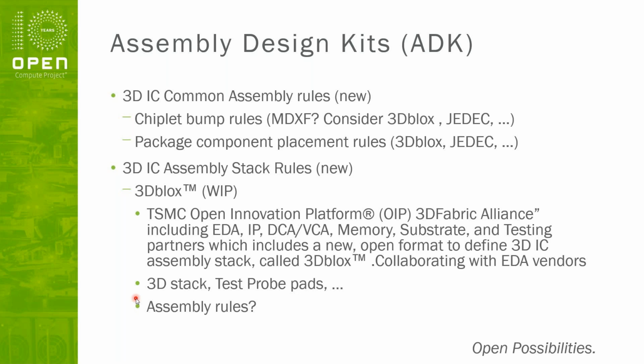One of the things that is not addressed in MDXF are rules outside the die. So this is more in the package, different rules. It may be die-to-die rules and spacing to mechanical components. There's a whole slew of other connectivity or rules that need to be defined, and they're not within the scope of MDXF. So this is going to require a new format. It's our understanding that Synopsys does not plan on supporting this. That could change, but that's our current understanding.